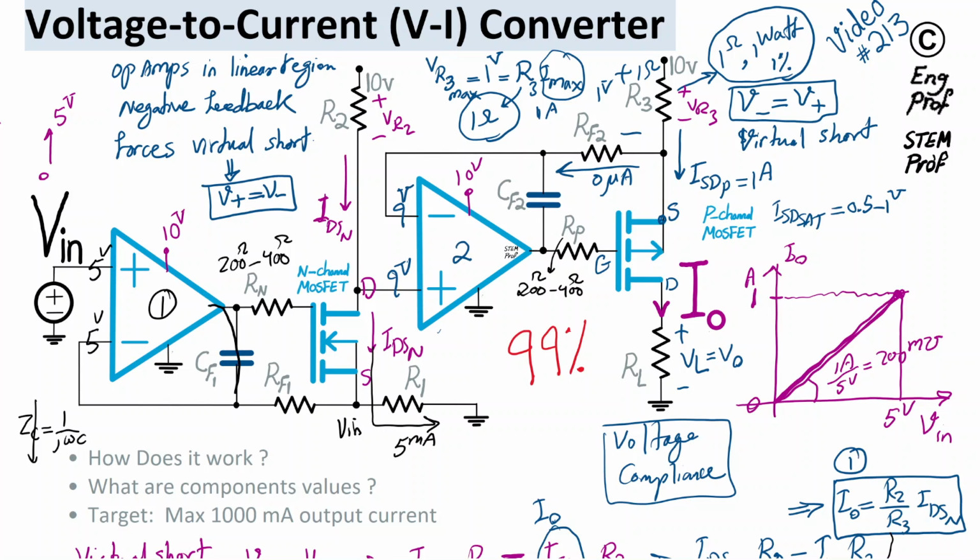What it does, for those frequencies and above, is directly connect the output of the op amp to the negative input terminal, sort of acting like a buffer. And with that, it basically forces the same voltage at the gate as at the source for those frequencies. So VGS is forced to 0, the transistor is shut down for those currents, and basically nothing passes to the output of the circuit because effectively for those components the MOSFET is not responsive. Okay, so that's for stability reasons. The time constant will be defined mainly by the product of RF1 and CF1, if that matters in a design.